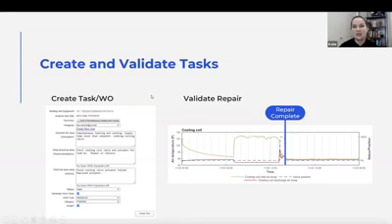So you're not doing a lot of writing things down on pieces of paper. We need to be moving into things being tracked in a database, resolutions tracked, and issues closed. So whatever type of interface they have, whether it interfaces with your work order management system or not, whether it's an embedded module, those are all things that you can talk through within your organization of what you think is needed, but then also what your providers can actually do. But the most important thing is that you can see that the repair fixed the problem. So you go the next day, you open up your diagnostic, and you see that the repair was completed at 2 o'clock that day. And you see that you no longer have that temperature difference across your coil.